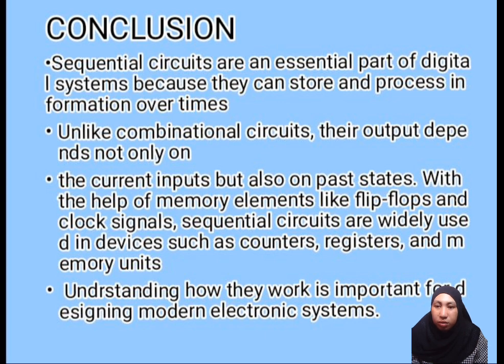Unlike combinational circuits, their output depends not only on the current input but also on past states, with the help of memory elements like flip-flops and a clock signal. Sequential circuits are widely used in devices such as counters, registers, and memory units. Understanding how they work is important for designing modern electronic systems.